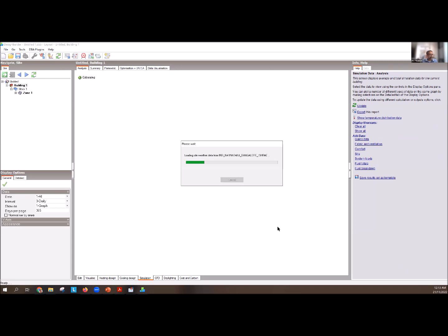And I can show you where to pick the... now, when architects talk about cooling loads, engineers get very upset, because when engineers talk about cooling loads, they talk about peak cooling loads. Otherwise, they talk about cooling energy, thermal energy. Okay. I'm fine whichever you choose to do, but just be clear about what you are looking for.